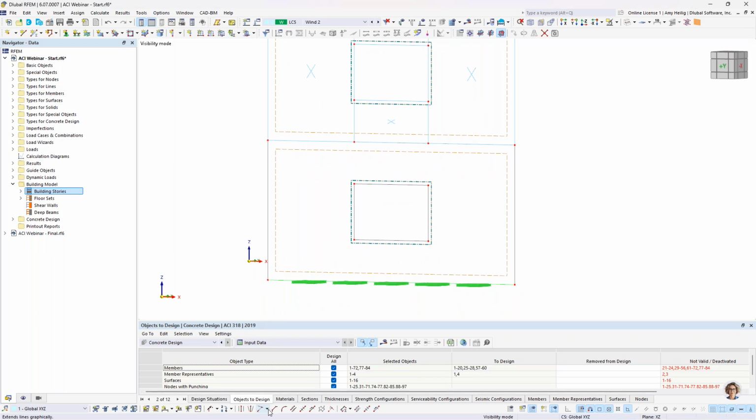It's in the program. With our drawing tools down at the bottom, we have this option to extend the line graphically. So something that you might find similar in AutoCAD. When I choose this option and I hold down the Alt key on my keyboard, what will happen here is that the program will automatically extend this line when I click on it, the upper left and right hand sides, without affecting the opening. And I'm going to do so here at the bottom right and at the bottom left. And now you can see that those line elements are automatically created again without affecting that opening. And the surface cells were automatically detected when we do this. So in case you have a shear wall with openings, you certainly want to take this workflow.